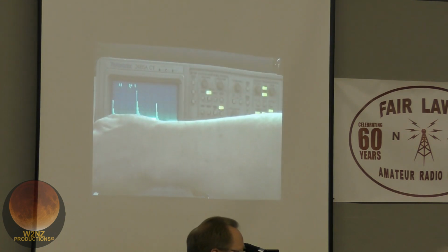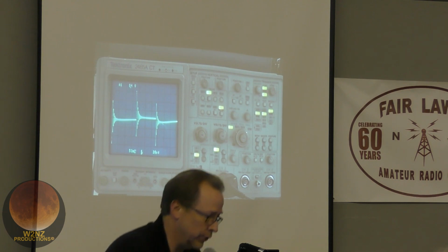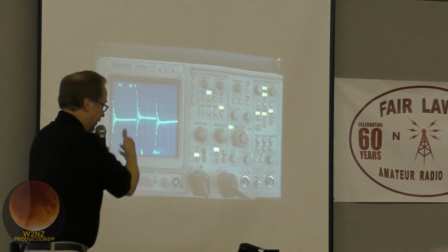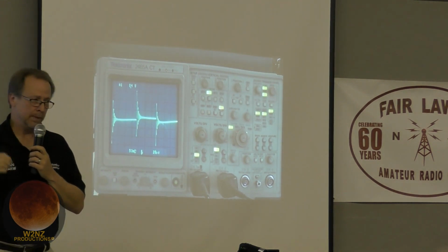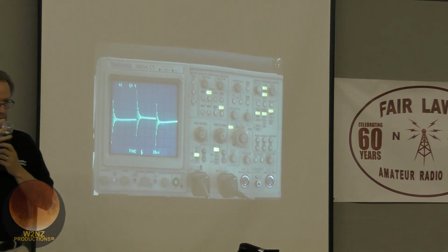So what's interesting is that oftentimes you'll use AC coupling when looking at DC circuits. Okay, so it's not like the voltmeter where you use AC for an AC range or DC for a DC voltage. Here we're just talking about the coupling that we're using to affect a certain measurement. So oftentimes we'll use an AC coupling to look at the small little variation sitting on top of a supply rail. Similarly, we'll often use DC coupling when looking at AC signals.